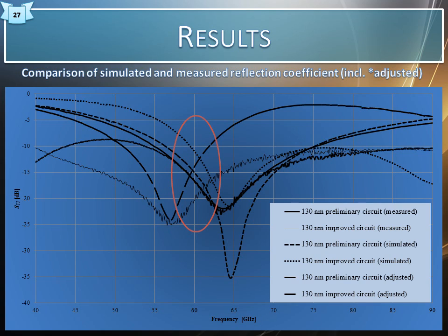This slide presents the noted shifts of the S11 reflection coefficient when comparing simulations and measurements and the adjusted values, where the modified or improved circuit of the Foster canonical form is used to determine the cause of the shift in this resonant frequency. Such an investigation could then suggest where and how these shifts occur and what is responsible for the changes.